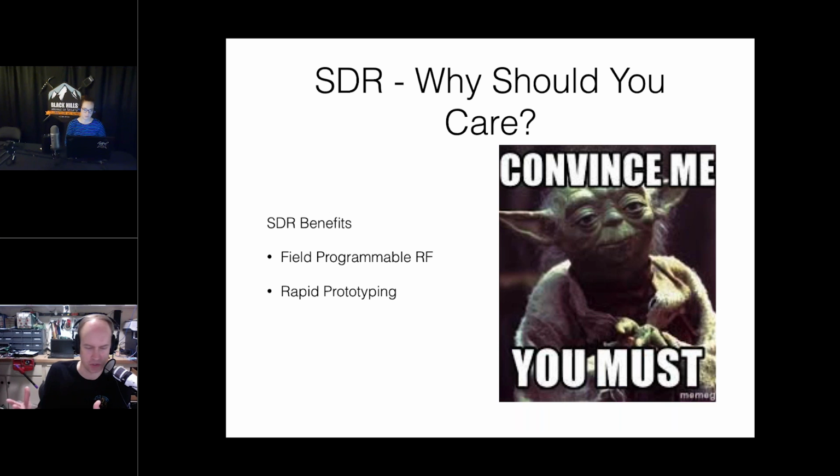If you're an engineer building radios, you don't want to spend 2 weeks spinning a board, sending it out, getting it back. You can actually use an SDR, as we'll see later, to prototype a new radio design in minutes in some cases. And then the thing that we'll probably care most about with this audience is reverse engineering and the massive leap forward in capabilities we have to do reverse engineering with SDR.